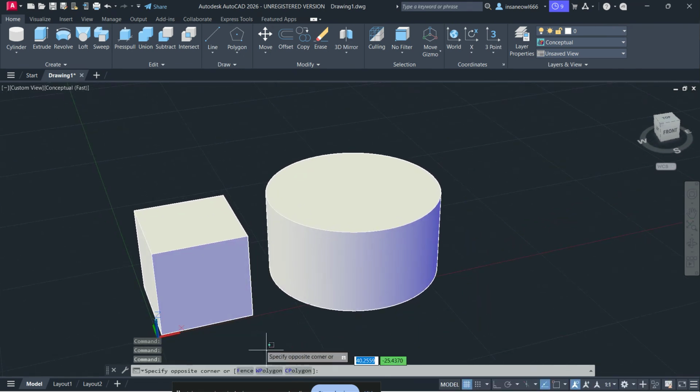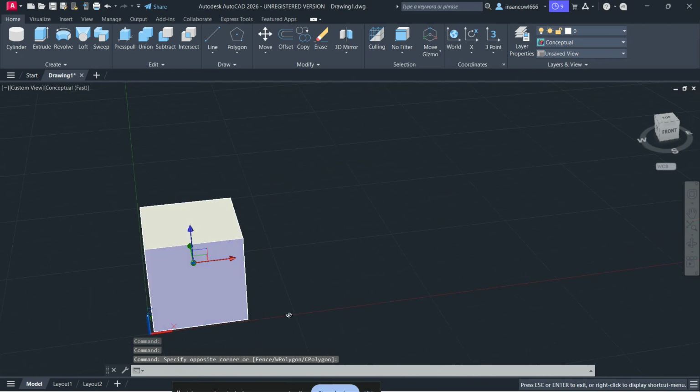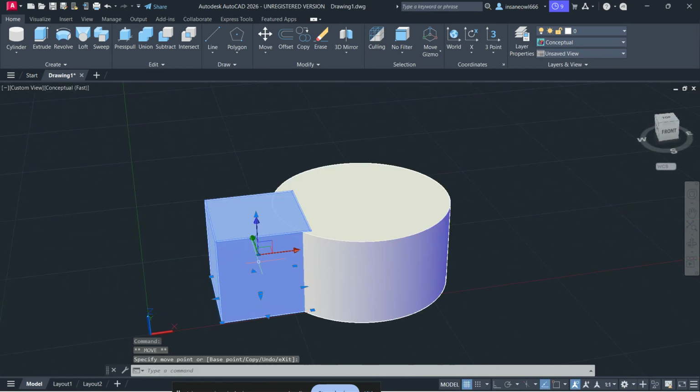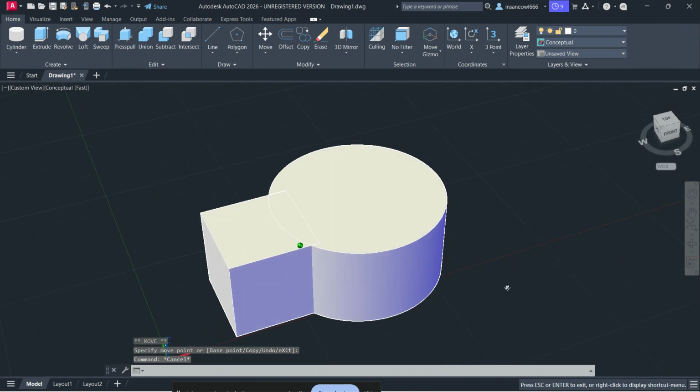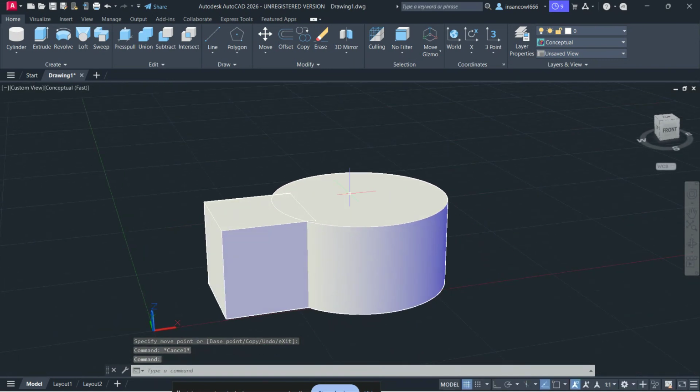Another common cause is vanishing faces. This happens when an operation makes a face or edge shrink down so much that it essentially disappears. Once that boundary collapses to zero size, the software no longer has enough valid information to complete the operation. A third cause is dirty geometry. Over time, solids can collect tiny redundant edges, slivers, or leftover geometry from previous Boolean operations. These small imperfections may not be obvious on screen, but they can absolutely interfere with new fillet, chamfer, and offset calculations.